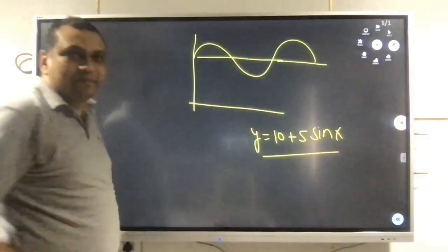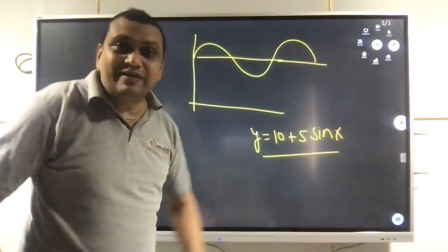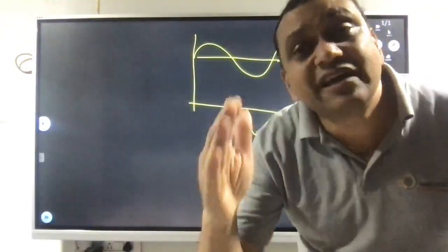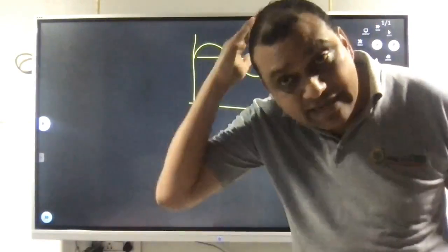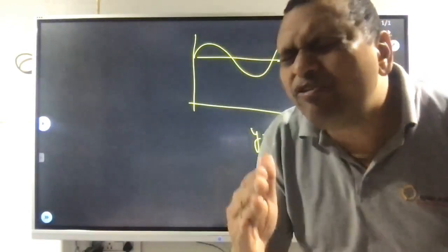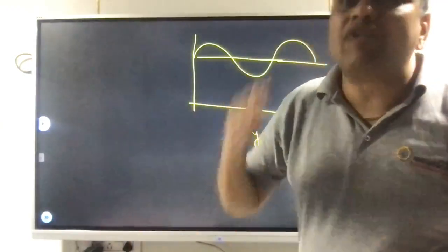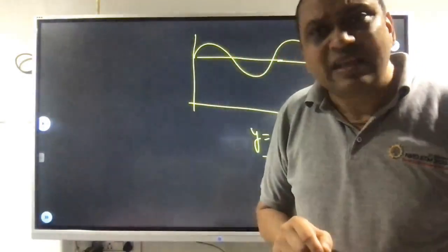This is the curve. Now in that case, what will be the CLA value? Remember one thing: if the cutoff length is not given to you, wherever the sequence of events is repeating, you take that as the cutoff length.